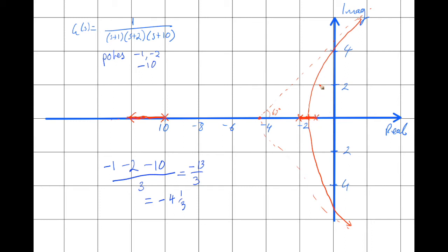So here you're going to have some trade-off between improving the rise time. If you go up here, you get very fast rise time, but quite a lot of overshoot and a slower settling time. So that might be the kind of trade-off that you're looking at. However, no matter where you go along here, you're probably going to get some steady state error. So let's say you might choose some particular pole locations up here, and then as in the previous example, you can substitute that value in. You can have a guess at what that value is, and substitute in here and work out what the gain will be. But how would you actually eliminate the steady state error?